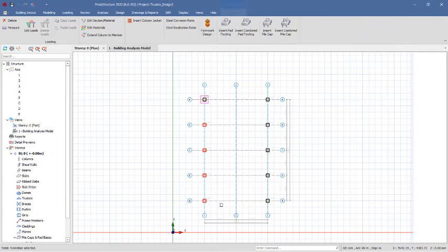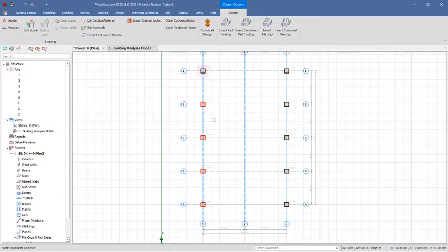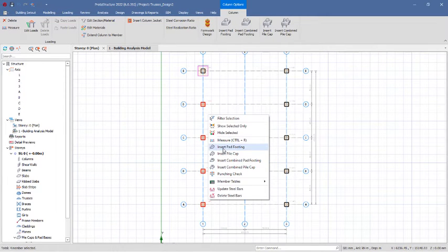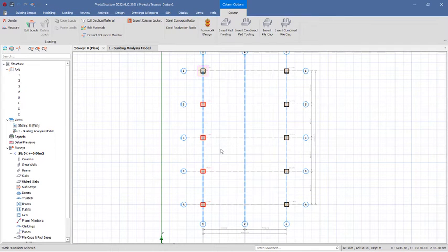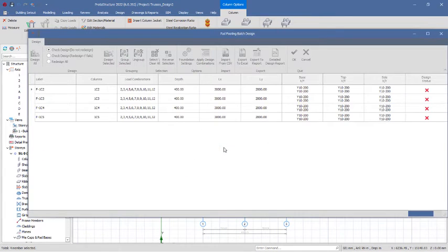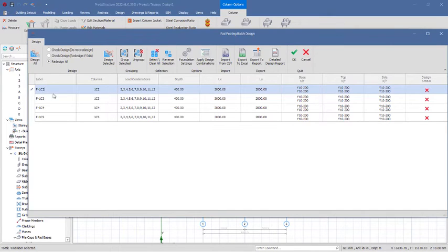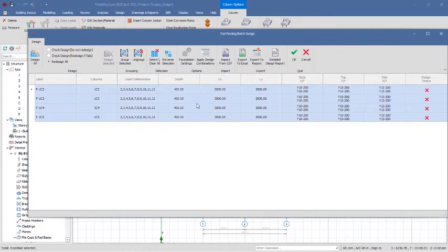So we can actually square it right here and then turn this up to 1.2. Take this to 1.2, so I have a square footing just like that. Okay, we can come to 3D right here, and then you'll be able to left click, right click, hold and turn this, so you have the reinforcement arrangement just like this. During the settings, we are able to set this to be a single reinforcement and not a double reinforcement. So you can see, click on the OK options to insert this footing. So this is a single column foundation design.